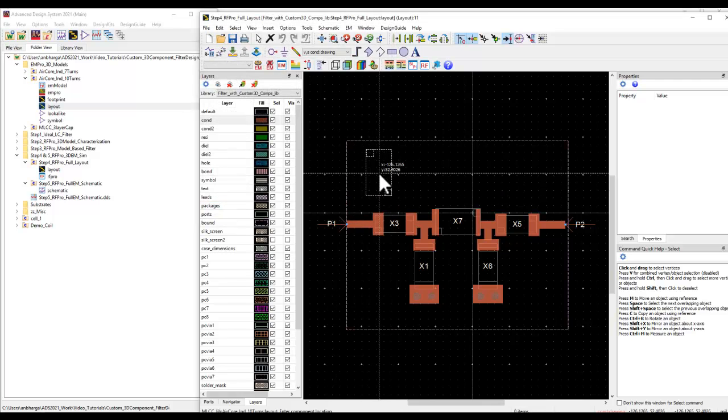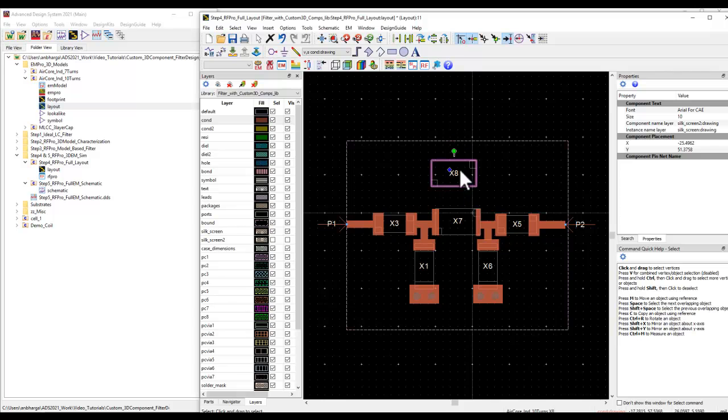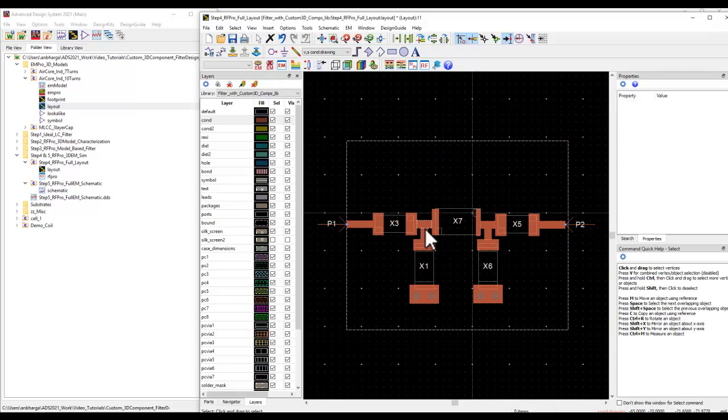In case you haven't taken care of orientation, like in this case, originally when I modeled, I thought I would prepare the PCB in this direction, but later I ended up designing the PCB in this direction. So this element is not at the right angle. I can take this model, just press Ctrl R, and rotate it so that I can place it properly. So not a big deal, pretty simple.